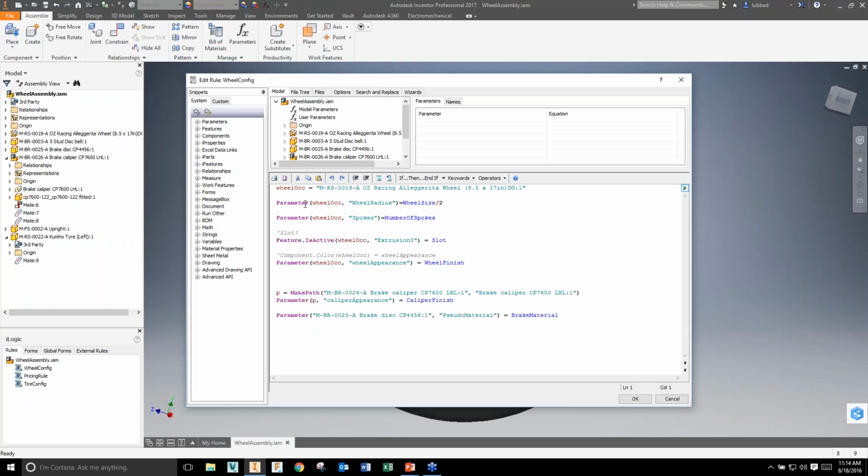So if I look at my model, how did I design that? For those of us who have seen CAD, you start with a sketch, you apply dimensions to that sketch. Well, why not be able to program information so that dimensions can change based on other dimensions changing? And that's exactly what we're doing here. We're saying, if I change a variable called wheel size or wheel radius, just divide that by 2 and make this other dimension half that size. That's all we're really doing here.